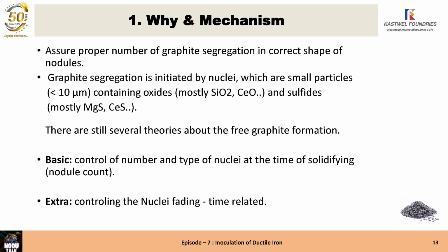So, why do we inoculate? It's good that we remember it and we realize it. It's to assure that we have the proper number of graphite segregation in the correct shape of nodules.